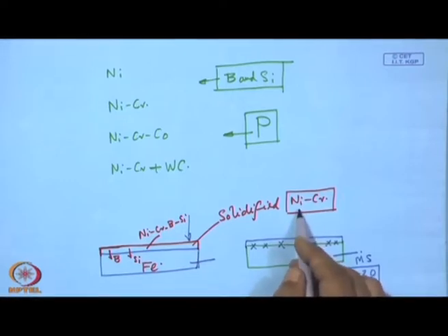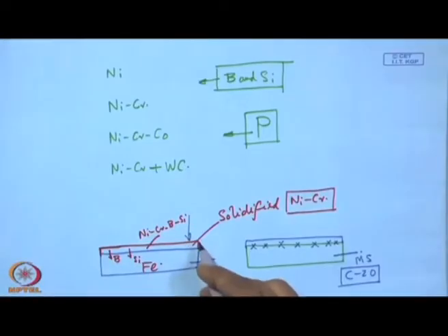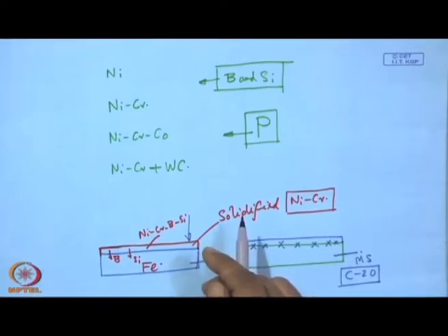Now the liquidus point is raised. So, the conclusion we can draw is that this material now cannot be melted and has some high temperature operation capability, because of the migration of boron and silicon from the parent material. So, these materials are sometimes also used for step bonding or step brazing process. Once it is melted, its melting point or liquidus point is automatically raised.